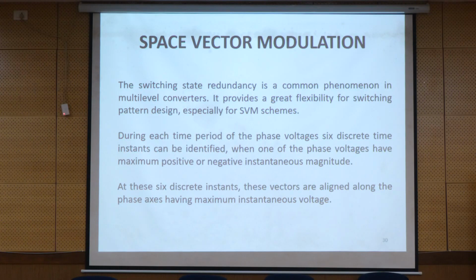These are all practical switches. Practical switches will take certain time to come to the 0 state. To be completely turned off or completely turned on, there will be a time delay. That time delay will be provided with the redundant switching state. The complete turn off process or complete turn on process is associated with a time factor. The time factor can be achieved with the redundant switching states, so that stress across the switches is going to be reduced.